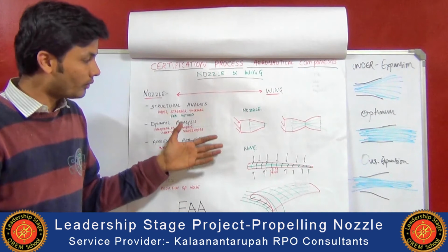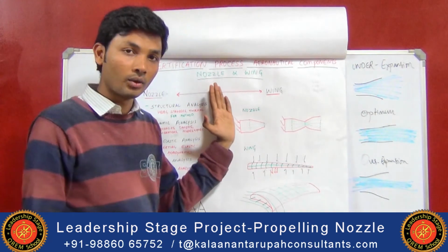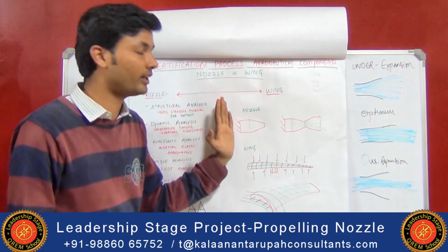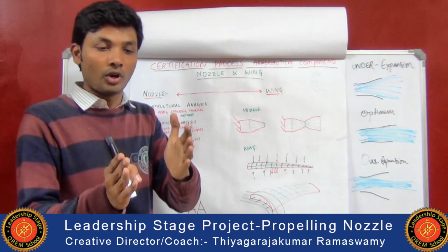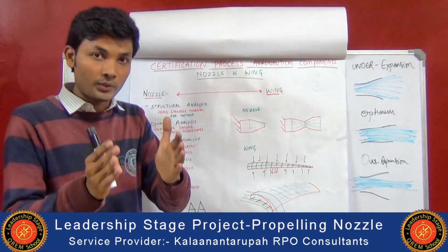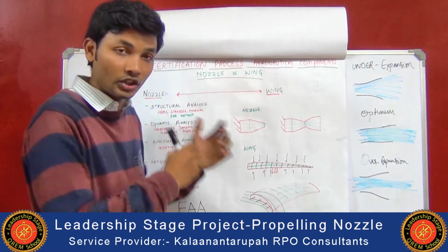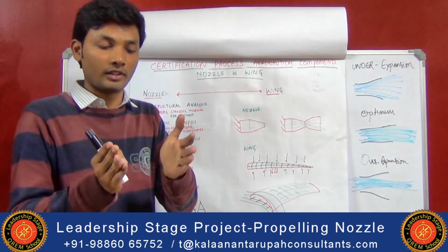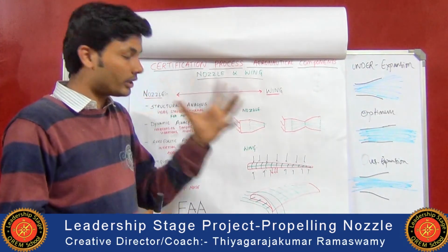So what we have to do is ensure the loads that are being directly applied on the nozzle should not make the nozzle displace its position, get deformed, or get fractured, which will directly change the direction of the exhaust gases, and in turn the exit velocity and the thrust. The change of the thrust direction is known as thrust vectoring. So that thing should not happen.